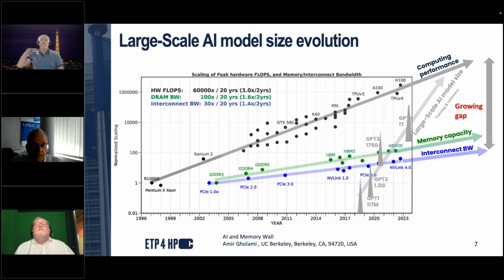One element on top of this that we see now with the growth of large systems and large processors is reliability. As we grow the reticle size, we start to go down lower and lower in nodes. And these advanced nodes, even at high altitudes in places like Denver or on mountaintops for observatories, we already see that radiation can have an effect on the processor performance. But the other effect we see is with large systems. Statistically, you have many more elements in the system itself, and so statistically, you're going to see more errors across the system as well. So addressing reliability in these larger chips and larger systems becomes very important.